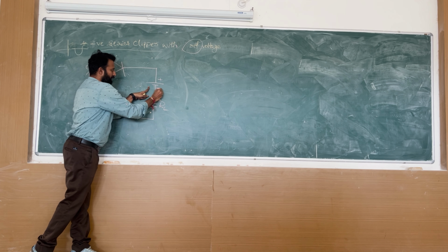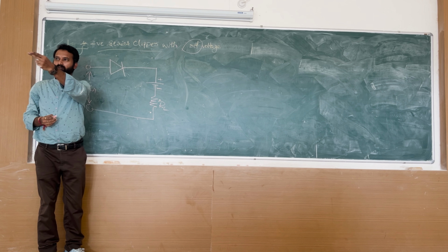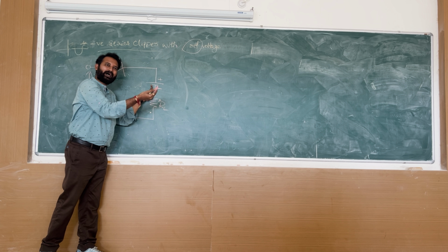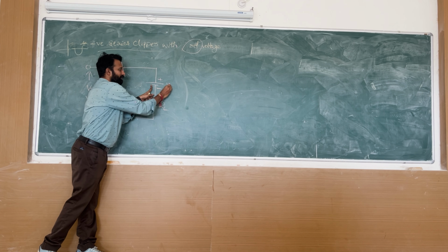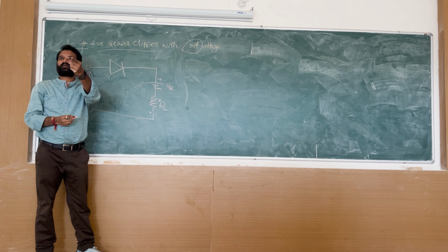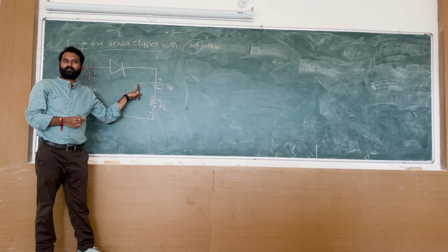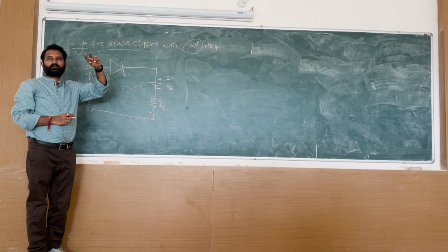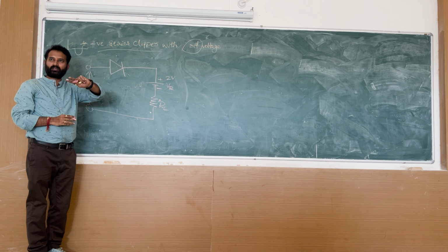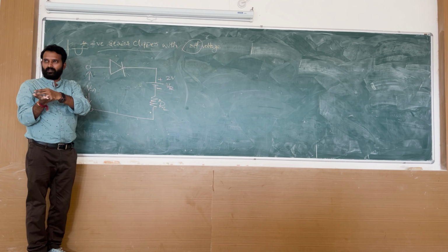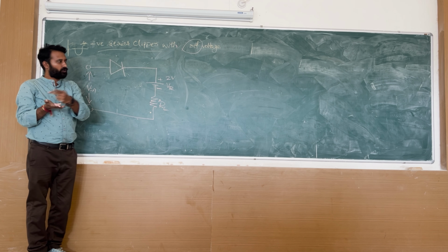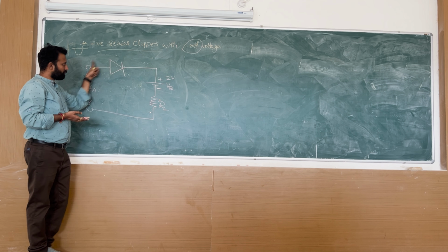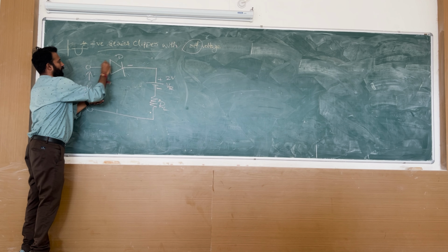And this reference voltage, someone has asked me, as a user, you will give this reference voltage. Here also you will connect a voltmeter or multimeter, and you are taking this reference. How much is that? Yesterday I explained how much it is. 2 volt. Maximum is 5 volt. Don't take the maximum reference voltage. The reference voltage should be less than 5 volt, more than 2, so that you can understand the diagram and the output properly. Understandable with this? What is this? Positive, negative. Anode.